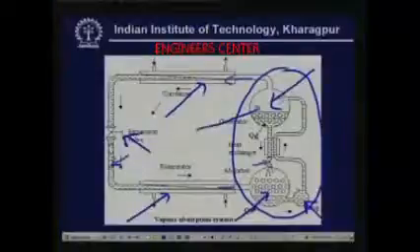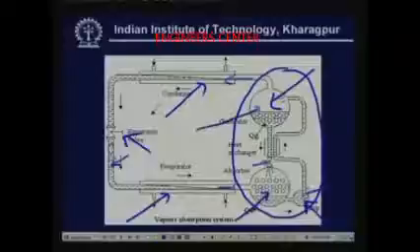So these systems are very convenient, very advantageous, where you have abundant sources of waste heat. For example, you can use solar heat, or you can use waste heat available in industries for providing refrigeration. So absorption systems have their own advantages. And you can see that in this particular absorption system, a small amount of mechanical energy is required to run the pump. But compared to a compressor, the work required here is very small,